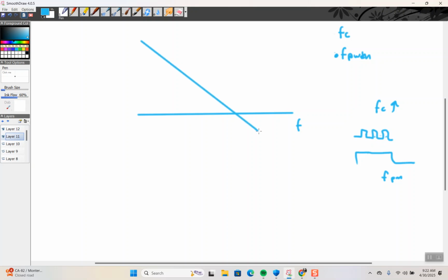So this is effective number of bits, and we get 0 when we are at the same clock frequency, right? And so the slower this is, the more clocks you can fit in, the more effective number of bits.